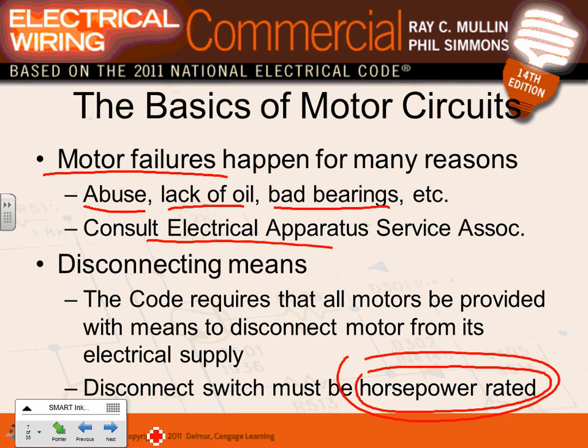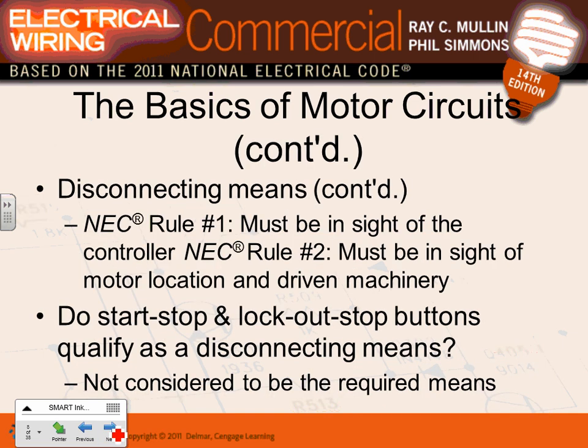You can interrupt the load with them. Not a big deal. So it becomes like it's 60 amp, 480, 277 at say 15 horsepower. So that becomes the rating given horsepower, the actual horsepower rating for your disconnect. We'll look at a couple of pictures in a second.